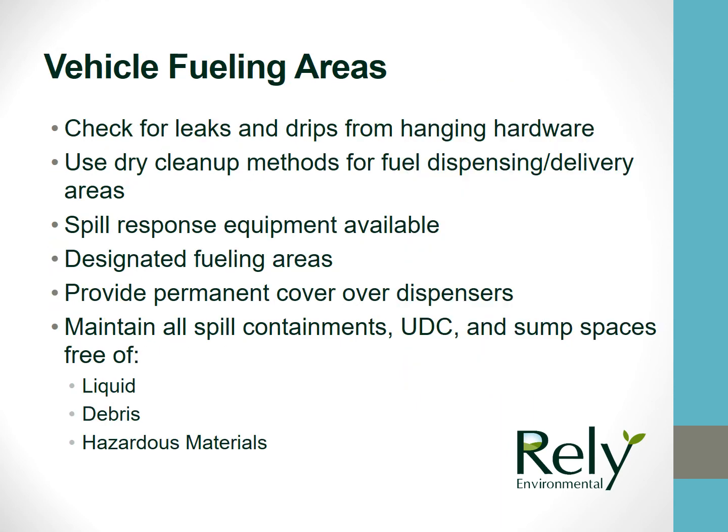In vehicle fueling areas, check for leaks and drips from hanging hardware. Use dry cleanup methods for fuel dispensing and delivery areas. Fueling areas should never be washed down unless water is collected and disposed of properly. Spill response equipment must be available and fueling should only be allowed in designated areas.